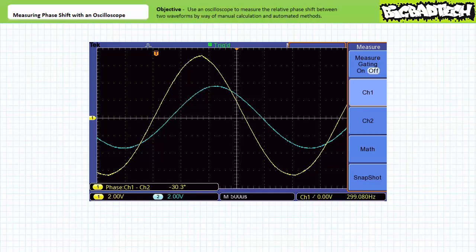Regarding the goldfish level of intelligence exhibited by this feature, also be aware of occasions in which a waveform clearly lagging by, let's say, 20 degrees is mistakenly measured as one leading by 160 degrees, or occasions in which a waveform clearly leading by, let's say, 15 degrees is mistakenly measured as one lagging by 165 degrees. Regardless, if you're well versed in phase shift as I expect you to be, you should be able to interpret these results. In short,